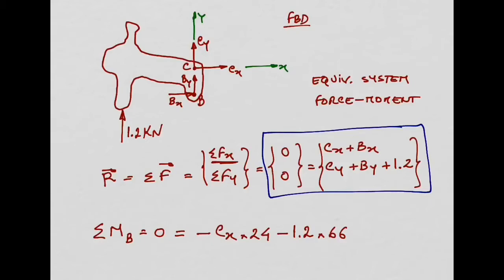What about units? Well, for the force we are working in kilonewtons. For the distance we are working in millimeters. So the units are going to be kilonewton millimeters for the moment. It's okay if you leave it at that, as far as you don't mix millimeters with meters. If you work with millimeters, everything needs to be in millimeters. If you want to work in meters, everything needs to be in meters. But if you work in newtons and meters? Yes, it's perfectly fine.